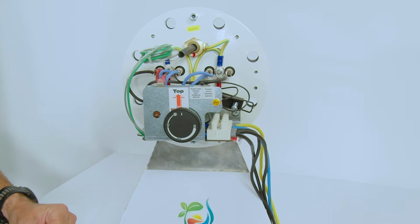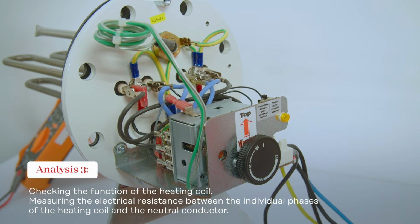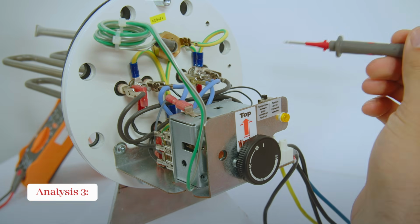We press it for a short time and that's it. If the temperature sensor has worked, then we will check the resistance between neutral conductor and phases of the heating rod. We have here a 2 kilowatt 3-phase heating rod, and therefore we expect a resistance of around 80 ohm.